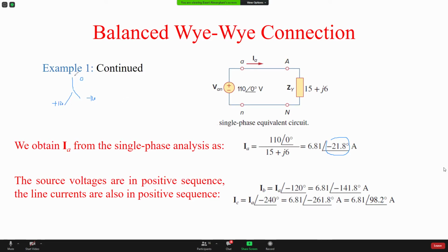So when you find the current in the first phase, the second phase current is the same equivalent circuit, the same voltage, the same impedances, the same thing, except the angle that is minus 120. So you're going to get the same magnitude, just minus 120. So what you do, minus 120, this minus 120, and this is plus 120. You got the three currents.